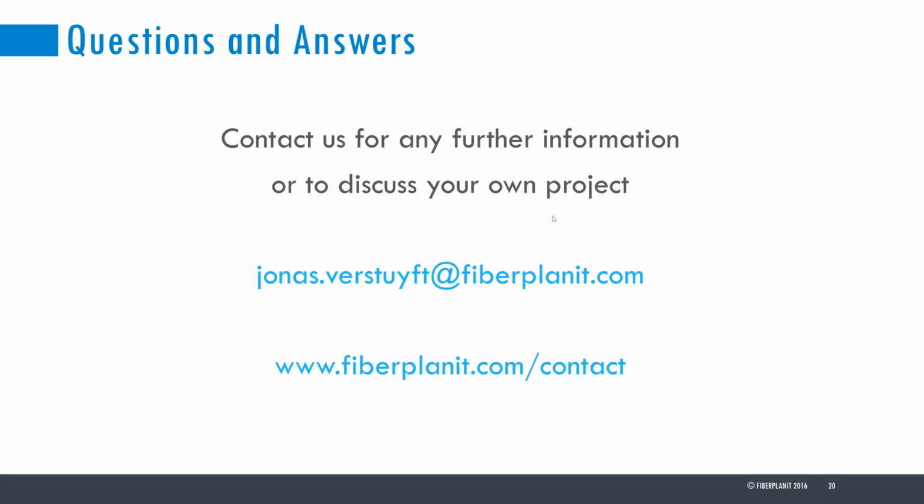So the GIS data that you saw in the demonstration is data we got from OpenStreetMap or generated ourselves. If you're talking about greenfield solutions, this can be a starting point, but if you want to get to constructible designs, you will need to do some sort of field surveying or use mobile mapping data to fine-tune your GIS data. Otherwise, there can be some inconsistencies when you go to construction.